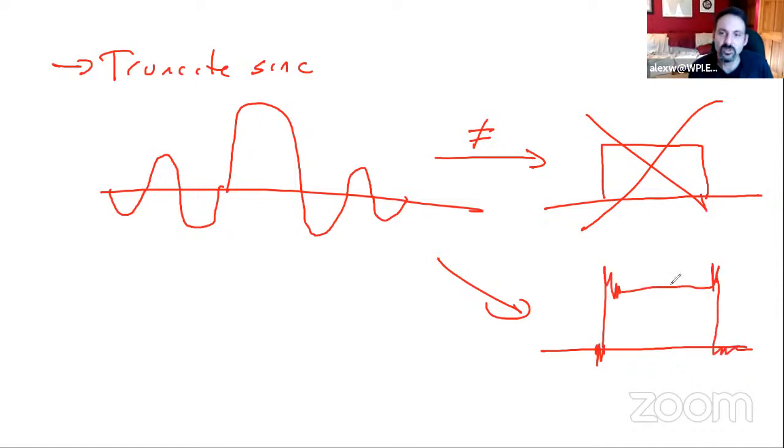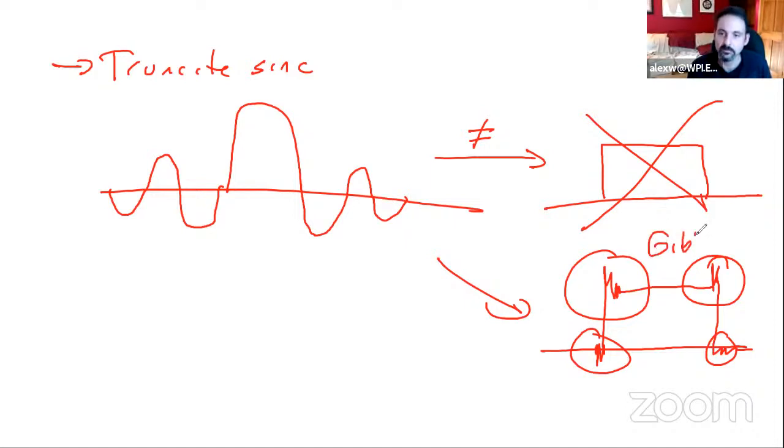You'll get these imperfections. We call it the Gibbs phenomenon. So it's not a perfect rectangular pulse, and therefore, if you sum copies of this, you're not going to get a perfect constant, and therefore it doesn't satisfy the frequency constraint of the Nyquist criterion for 0 ISI, right?